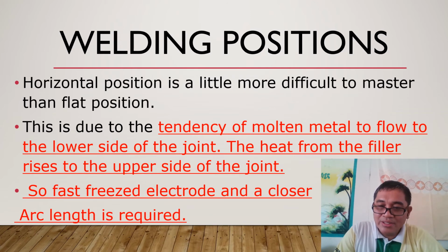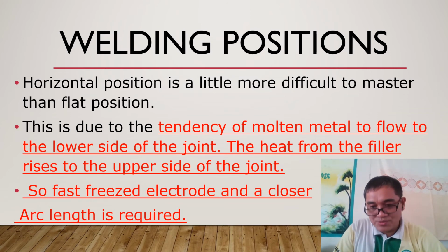So what's the remedy for this? We need to use a fast freeze electrode, and we need to use a closer arc length in order to achieve good performance in horizontal position. Okay.